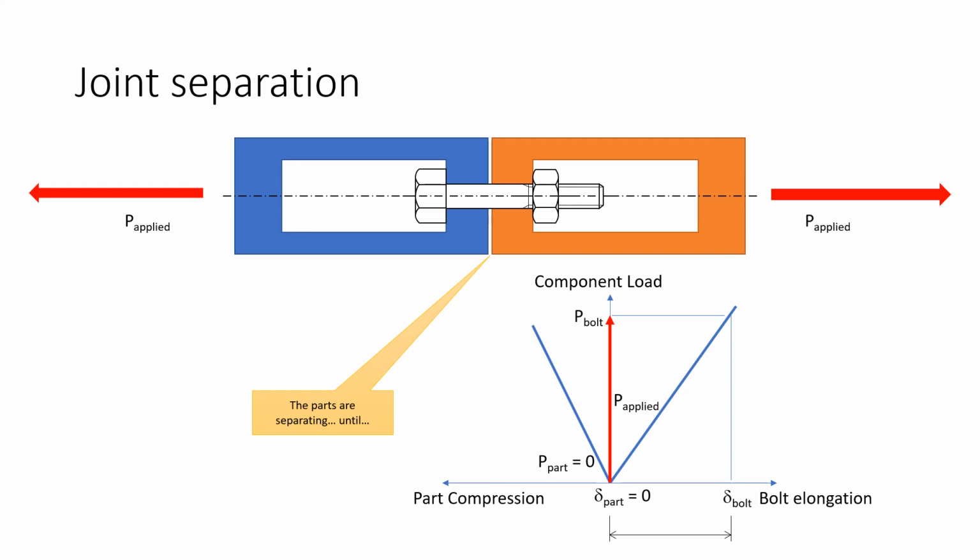With a bolt being a thing that has threads on it, stress rises. It's not really a good situation to have all of that being carried in tension on the bolt. So it is the reason why we try not to ever get into that situation. We try to make the preload adequate, and the knowledge of the parts being bolted and the stiffness of the bolts is used to make sure that we've got a good bolt design.